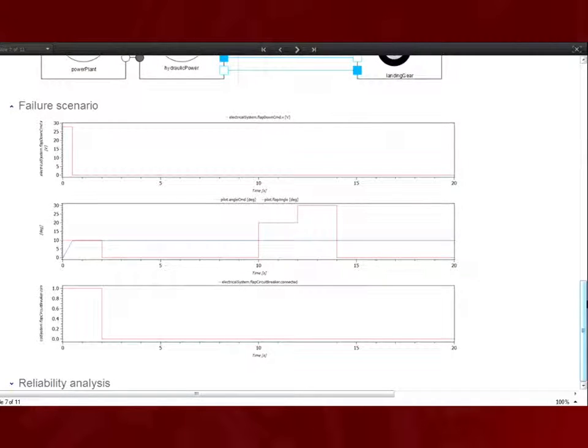So we can see that in the beginning, he's changing the angle of the flap, and then when he tries to switch it back, basically it's taking off, and once it's taken off, he wants to have the flaps in neutral position, 0 degrees, but that doesn't happen. Doesn't really matter that much because he's just flying more inefficiently, but when he wants to land, it's more important to be able to get him in a proper angle to decrease speed. But that isn't happening either, and this is because of an electrical failure.